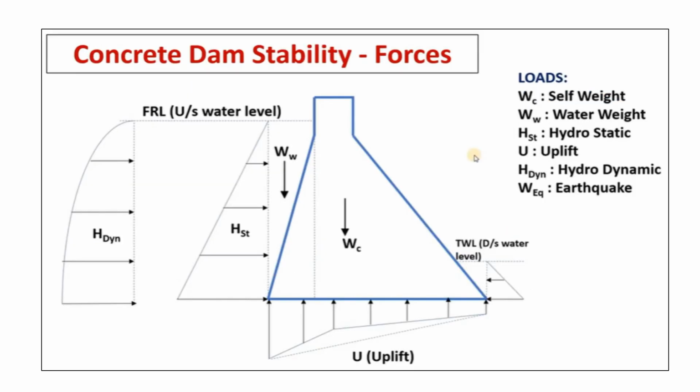Stability of concrete dam involves identifying different loads as shown here. Basic load is self-weight of dam. Then other important load is hydrostatic force of water and corresponding uplifts. Further, based on the shape of dam, upstream side weight of water can be considered if there is upstream slope.